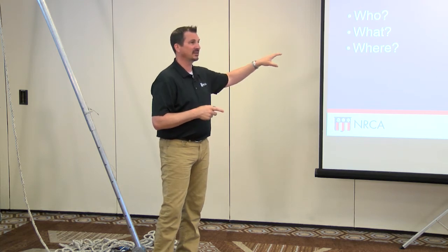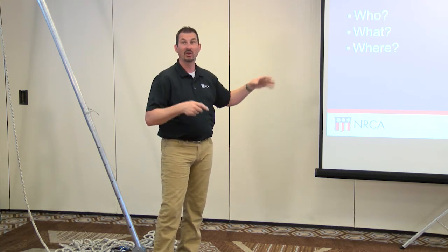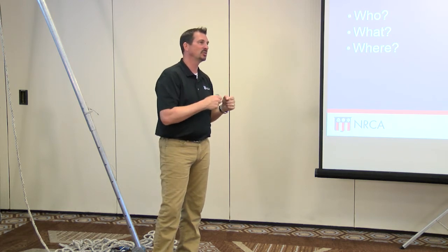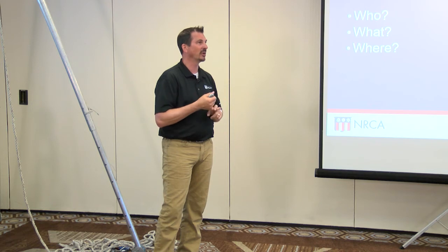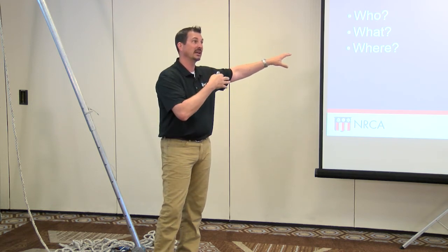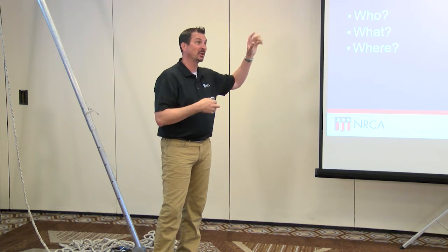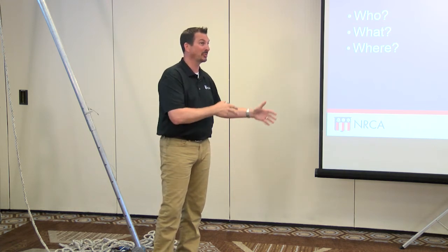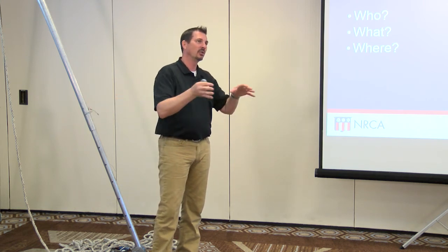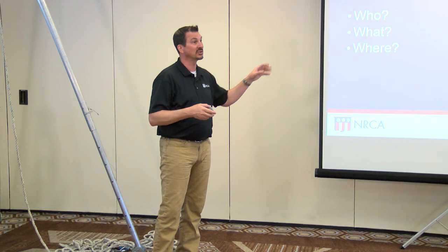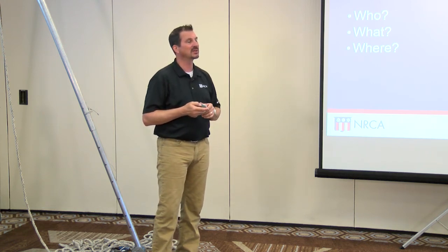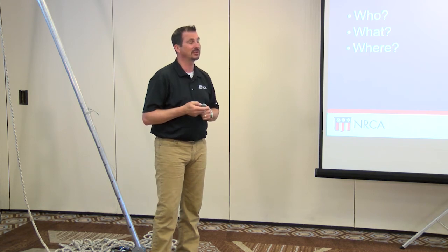The one downside of this is in many cases you may not be able to get into all sides of a building or in all those rooms in the inside of it. As much as you possibly can, try to predetermine whether or not you have any risks on the inside of a facility as much as on the outside. I mean, we've all done jobs where there's a computer room or an electrical room, or there's going to be people in a specific area that we may need to work over. Those are all risks we need to take into factor with a job hazard analysis. So try and get everywhere you possibly can. One of the best ways to do that, by including that facility manager or maintenance person.